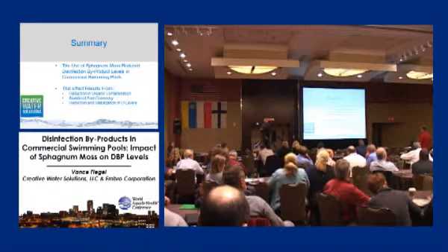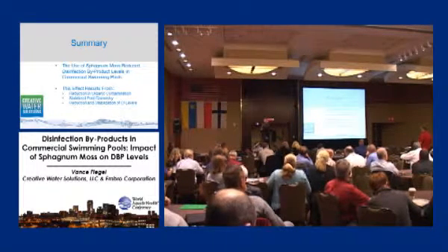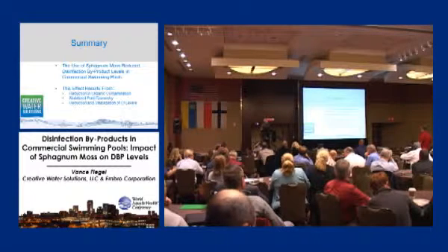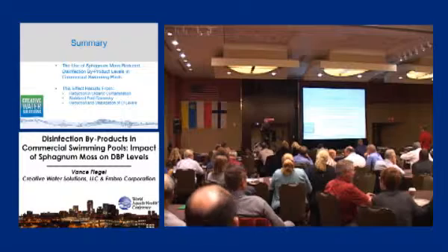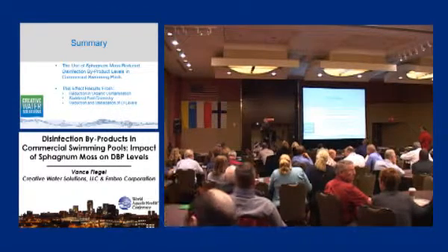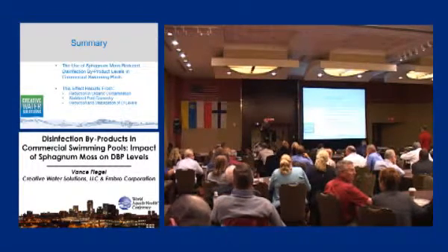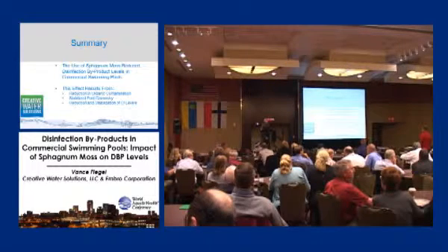Okay, and you mentioned that you request that facilities drop their chlorine values down to 2 parts per million. Correct. Is that a request or is that a requirement also? We don't require that, but if you do that, you're going to see more chemical savings than if you leave them up at 3 or 4 parts per million, depending on the facility. A number of facilities have gone down as low as 1.5 parts per million, but we don't require that.